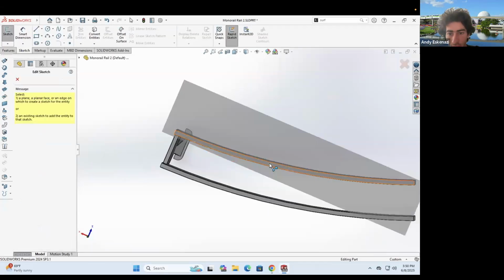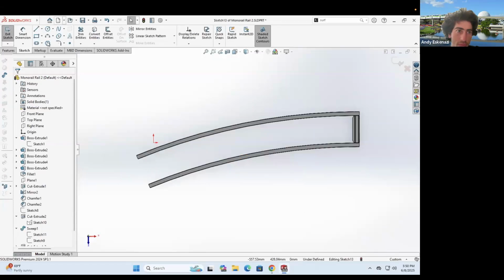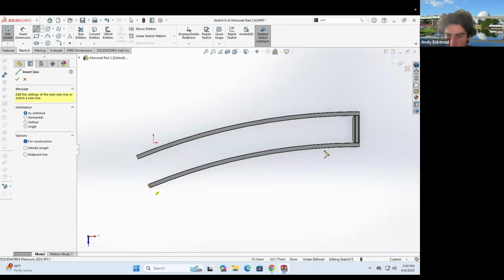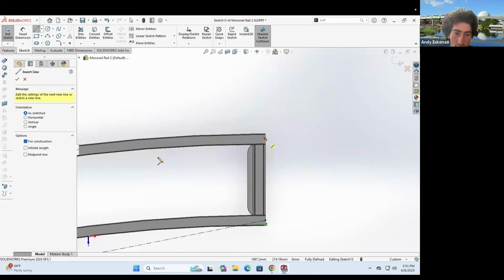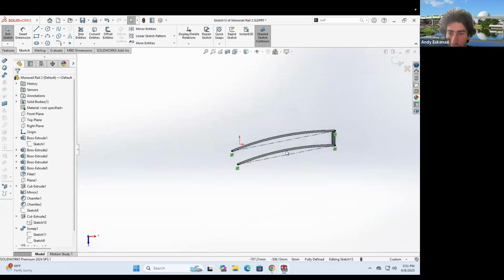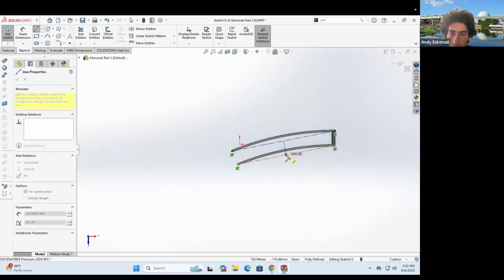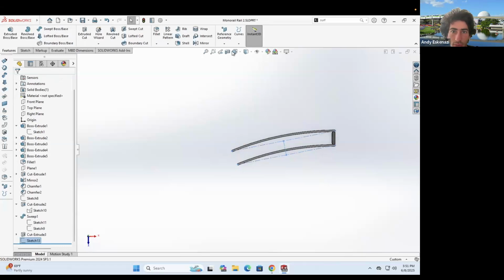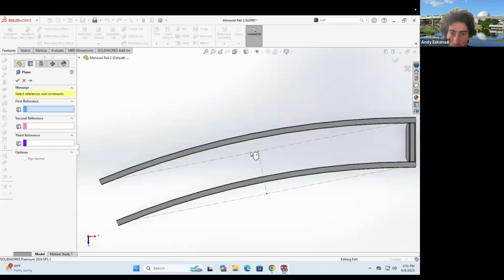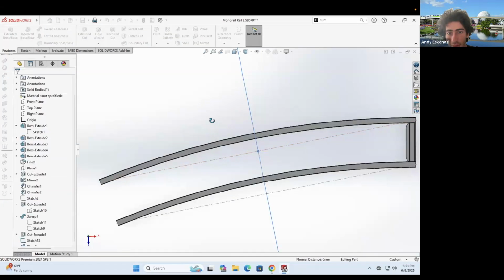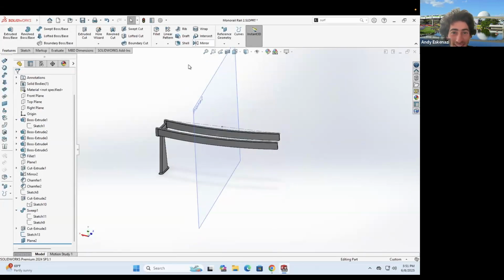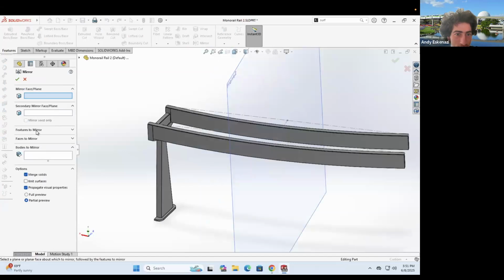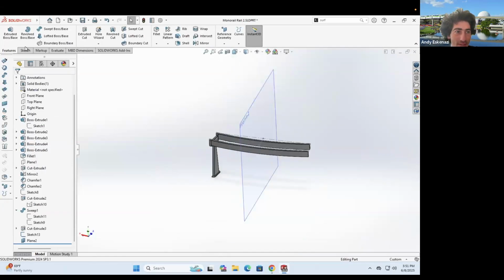So I'm gonna create a sketch right here. It's gonna go like this. Essentially, I'm gonna put a mirroring plane over here. And all right, so how am I gonna, there we go. Features, reference geometry, plane. It's gonna go right there. Perfect. And what are we gonna mirror? We're gonna mirror that. Let's see whether it works, right? Actually, no, we can do the classic. I think it's gonna be easier.